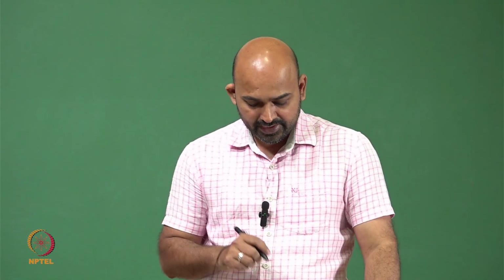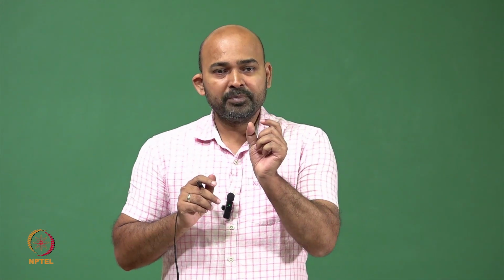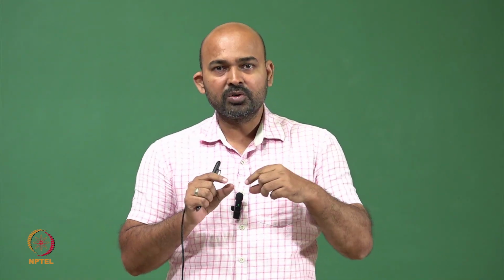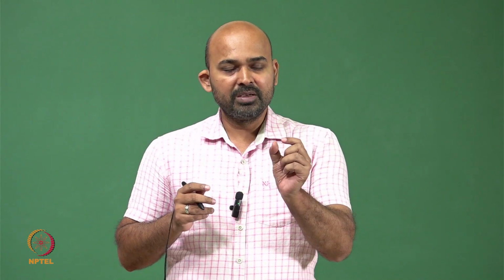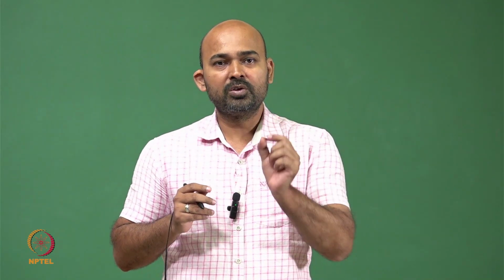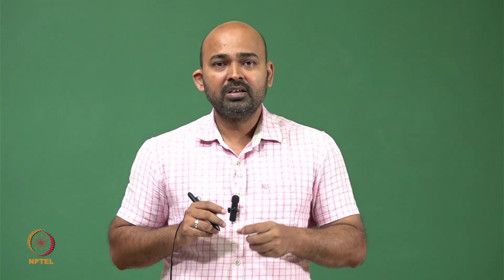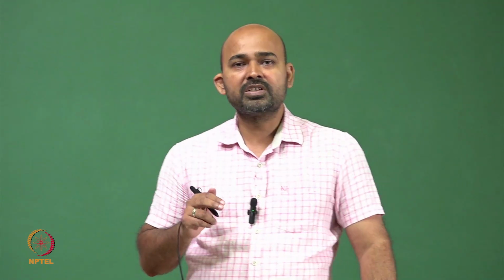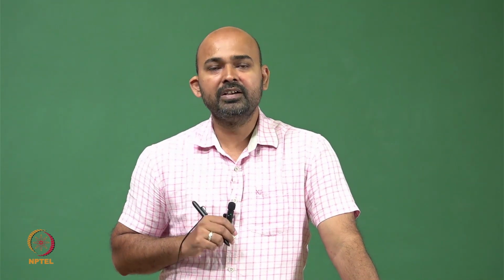So this is the SAW device, and usually when we design these IDT structures, the gap between the two comb-like structures is generally equal to the width of the electrode, so that the conversion efficiency is much higher if we keep that gap equal to the width of the electrode, which is lambda by 4, as we saw last slide. If we keep them lambda by 4, lambda by 4, the conversion efficiency of electrical signal to acoustic wave is much higher for an IDT structure.